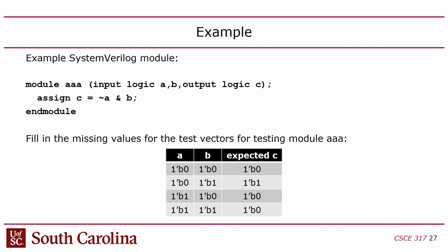So I'm not even sure when it would matter whether you use tilde or exclamation. I generally use tilde for negation in Verilog. But yeah, not A and B. Notice that's a single ampersand, which is the bitwise version. I believe Verilog also has the double ampersand, but when we're doing bitwise calculations, use single ampersand. And this just creates a truth table like the ones that you guys use in 211.